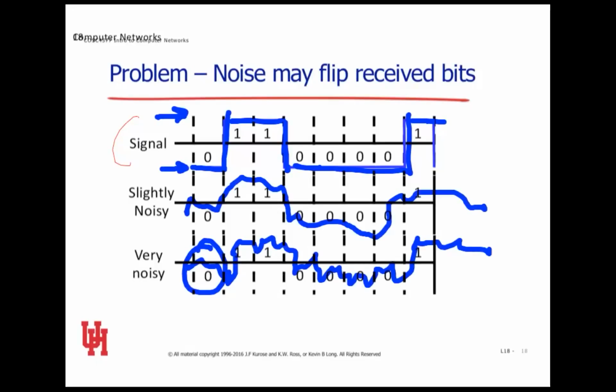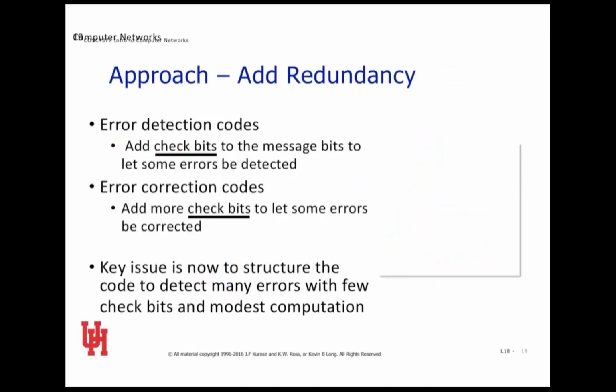So you'll put some space in between the high level and the low level, and you'll usually ignore things around the center point. You're going to create what are called guard bands here. So nothing below this or above this will be considered valid. And that gives you some room where this signal can be perturbed by running into noise, and it can be amplified or attenuated, and you'll still be able to tell it's a 1 versus a 0.